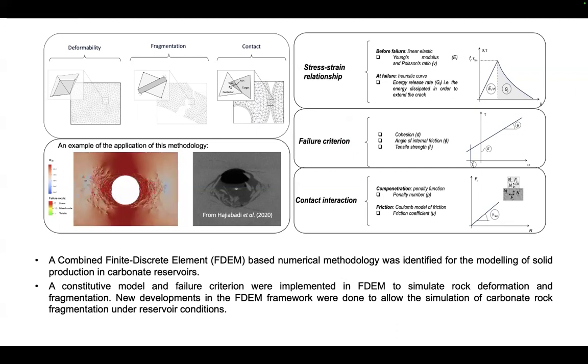The strength failure, yes. In this particular case, failure is a stress criterion. You measure stress at the joint element nodes, and depending on the amount of stress, the nodes release an amount of stiffness. They start being very stiff, so it's like there are no cohesive elements or joint elements between elements. Then when the stress reaches a certain value, for instance, the tensile stress reaches the value of the tensile strength, then you have opening allowed. The joint element loses its stiffness and there is an opening, and so there is a tensile fracture. The same thing in shear. For this particular model, for FDEM, that's how we describe failure.